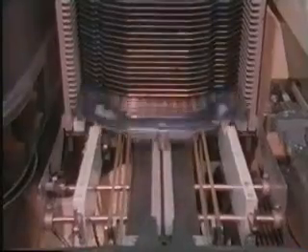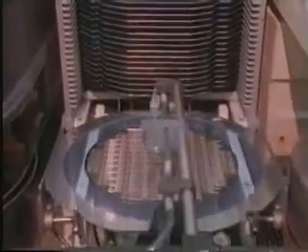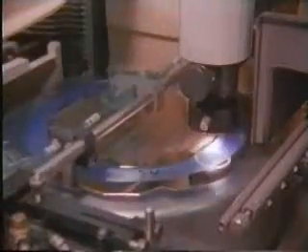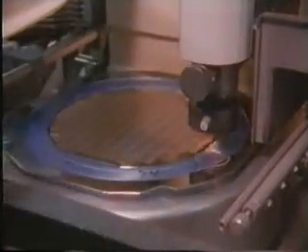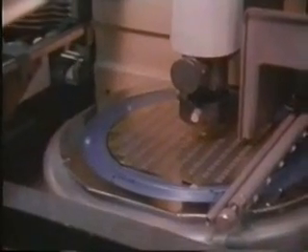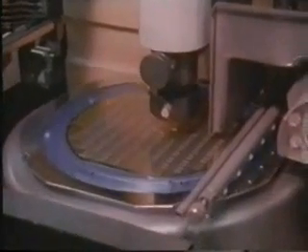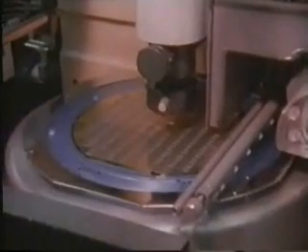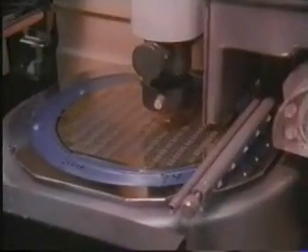Wafers are mounted on sticky mylar tape to keep them intact as the individual circuits are separated. An optical scanner aligns the wafer by checking specific points. Then, in soapy streams of water, a diamond saw cuts through the silicon wafer without cutting the tape beneath. The dies on the wafer are separated, but they remain attached to the tape.